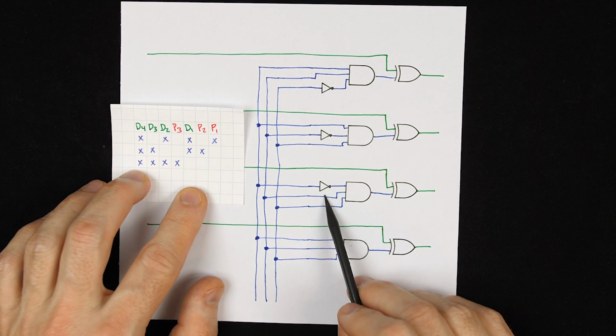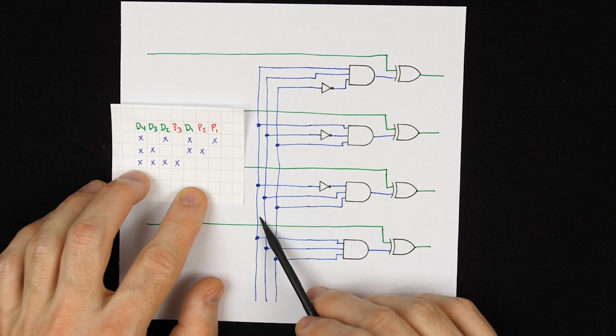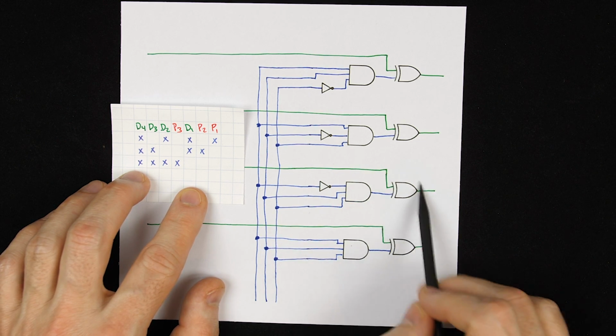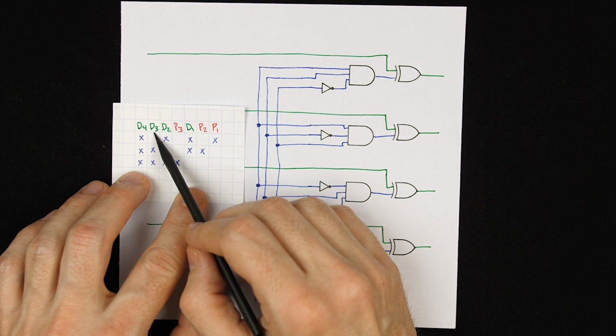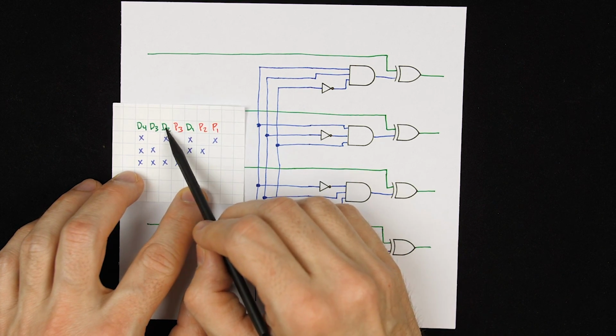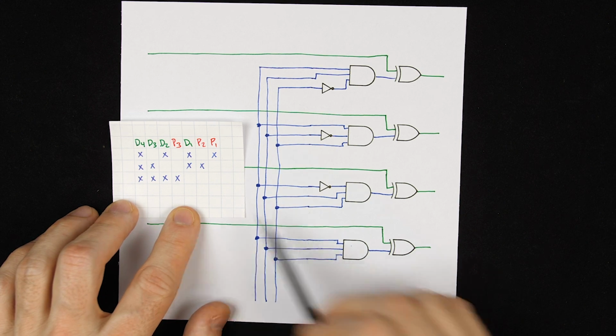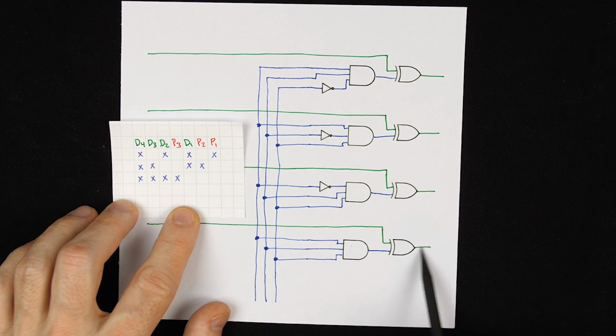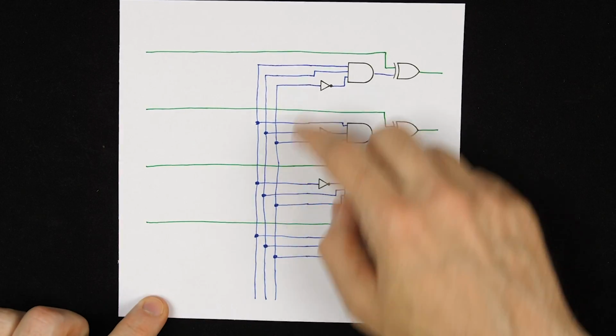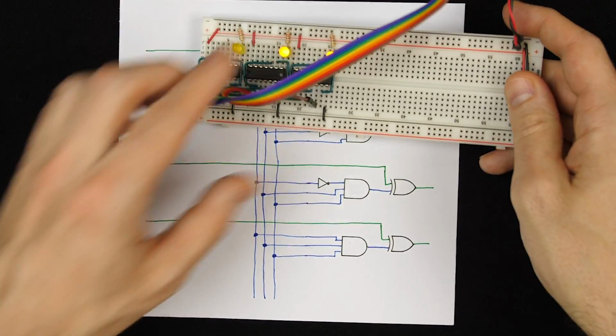Here we have a 1, 1, 0. So in the case that we've identified our error is in bit 6, 110, then we'll flip D3. We'll flip the 6th bit position, 1, 2, 3, 4, 5, 6. And then, of course, if we are 111, that's the 7th bit position, and we'll flip this last bit. So this decoder circuit will let us use the binary information we have.